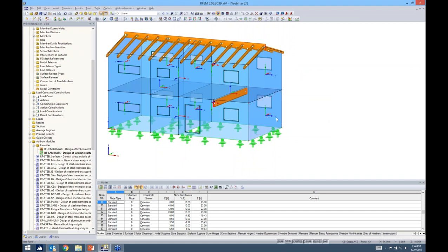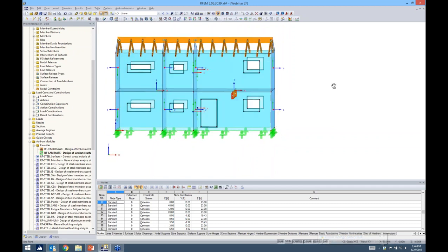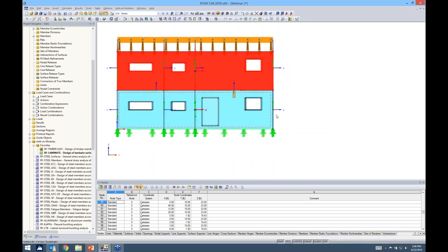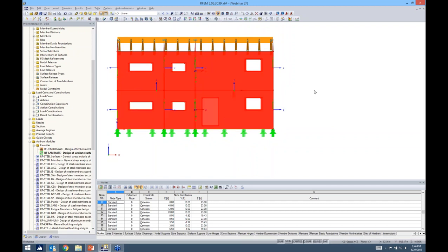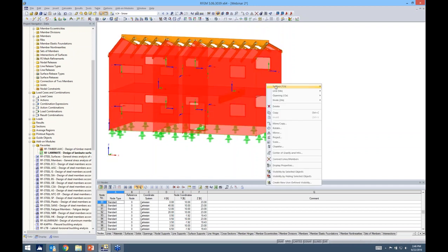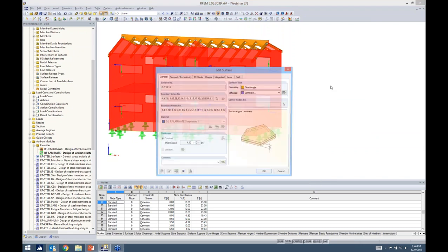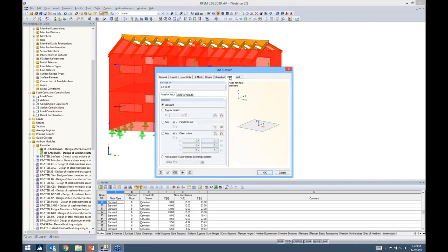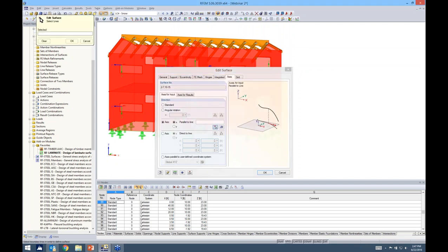This is not good. We want these strong layers to be oriented in the vertical direction to take those gravity loads. So I could sit here and change the orientation of all of these surfaces, but better yet, we have a quick feature in the program. If I just go ahead and select all of my wall panels, I right click and I go to Surface Edit, there's an option here called Axes. And under Axes, there is the option Axis here, and I can actually set all of my local x-axes parallel to a line that I choose in the model.